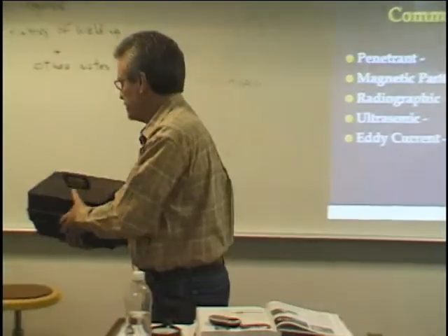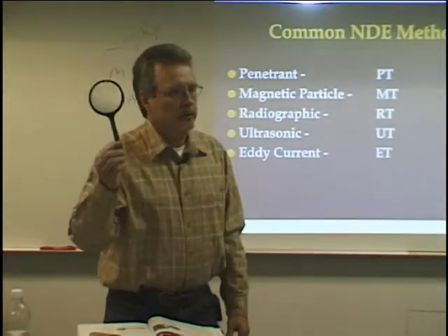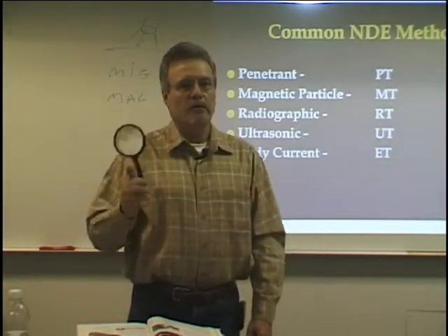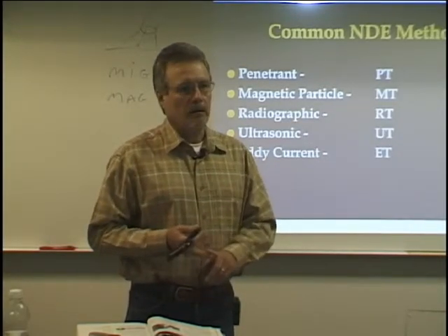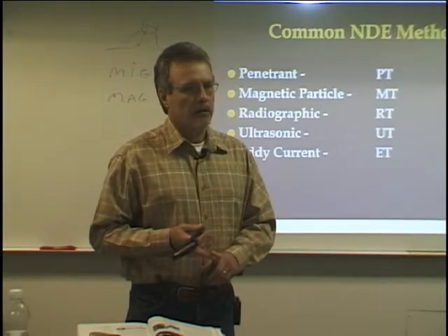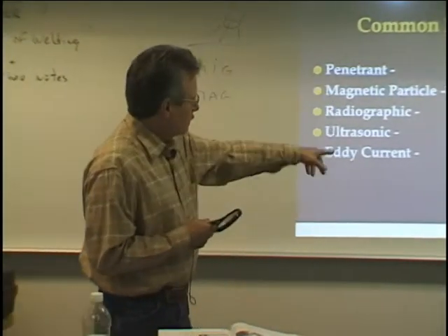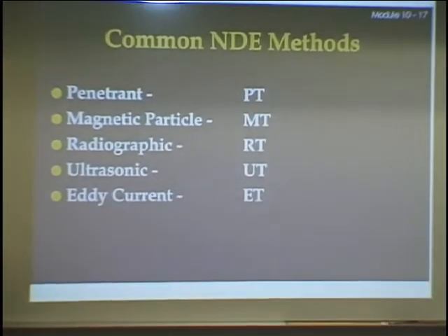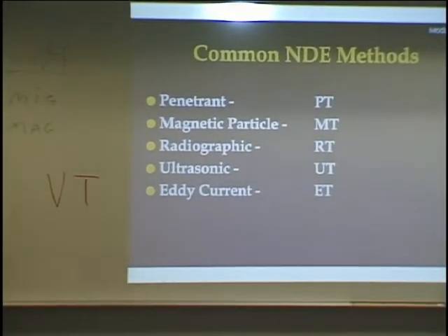But out of those testing methods, there's still several others, like X-ray and all of that. The most common one is this one, visual inspection: looking at something and being able to tell what's wrong with it. It's the cheapest, it's the most efficient, and when I go on a project, if I don't do anything else, I look at every weld. And you are your own best inspector, so understand that. Write down these abbreviations and know that VT, visual inspection, is the most economical, efficient, fastest, cheapest.